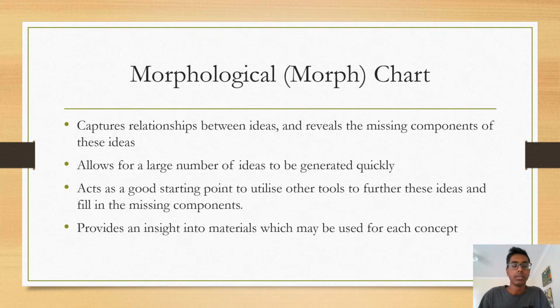A morphological, or morph, chart is a structured approach towards concept generation that is based around functional aspects that must be included in all concepts, as specified by the problem statement. The use of morph charts establishes numerous means to achieve a specific functionality. This chart helps team members identify the advantages and disadvantages of alternatives, and so effectively guides our execution of the project. A morph chart can produce a significant amount of concept solutions.